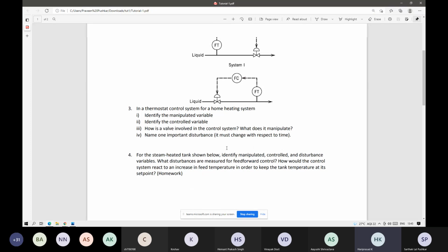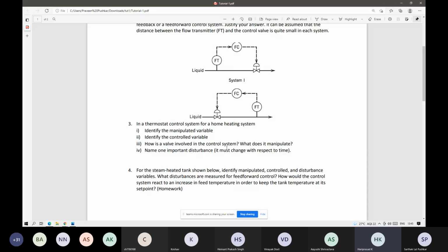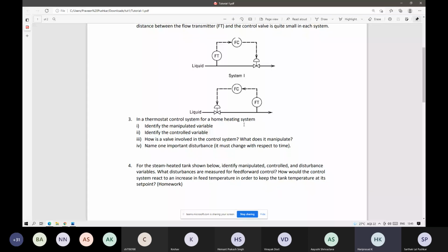As I told, these are qualitative statements. Got it? If you need a more tangible variable, then yes, it's the flow rate. But what is really happening is that the change in heat is being converted into an increase or decrease in temperature. So there is no harm in saying that heat is a manipulated variable, but the manipulation of the heat is done through the change of flow rate. Okay? Perfect. Any further questions?